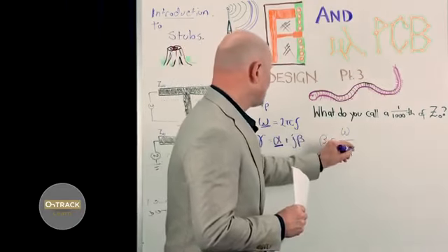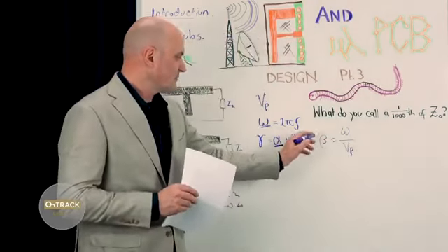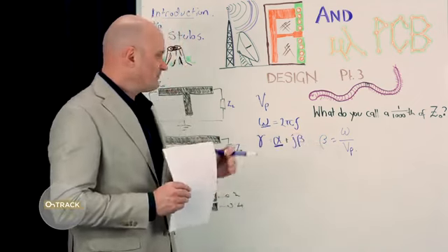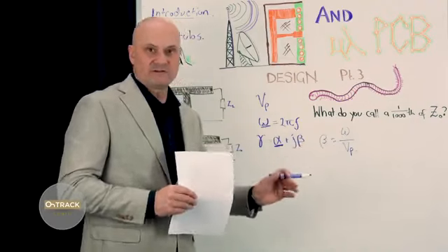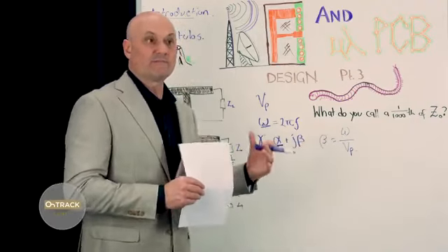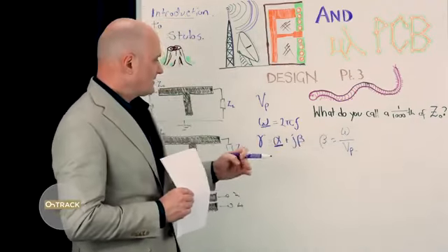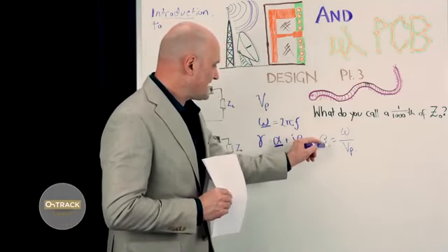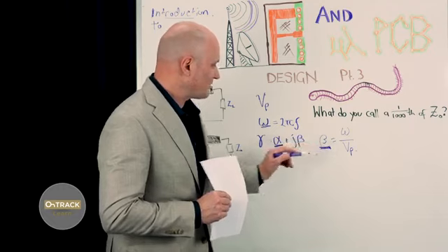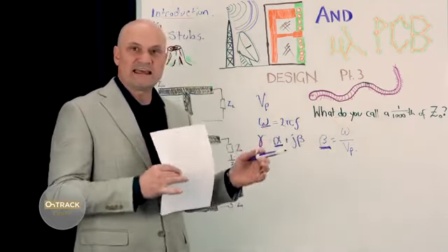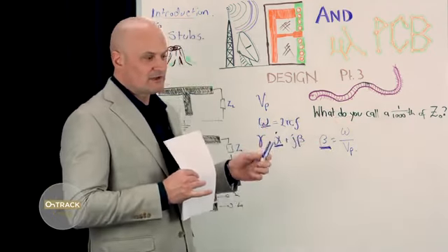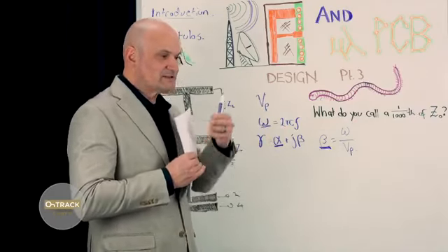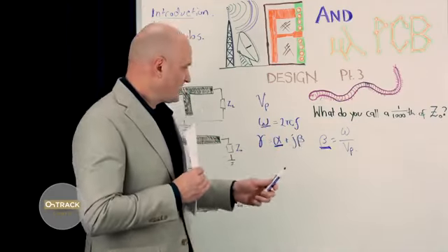This makes sense. What we're saying is we have this parameter beta that represents, at the frequency we're interested in or doing math around, for a given velocity, the angle it takes for a wave over a given length of line. For a given line length, how much of a wave angle is that?